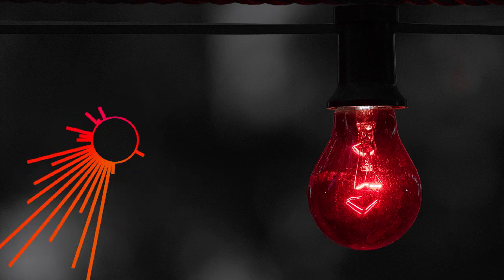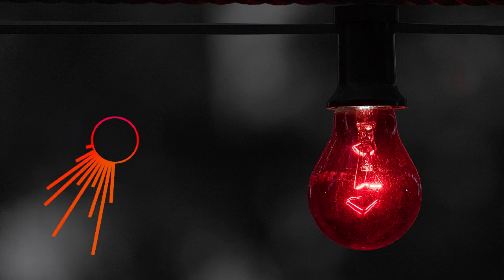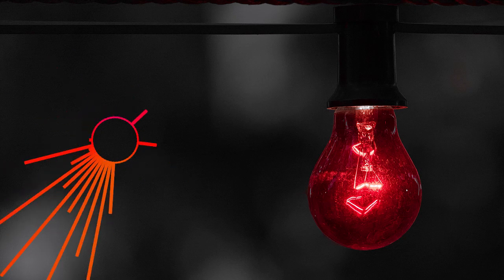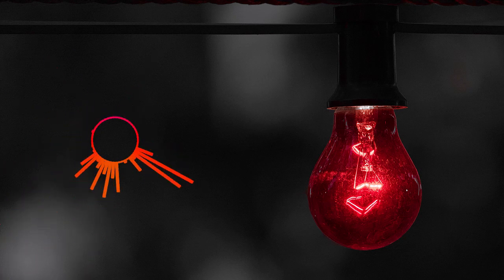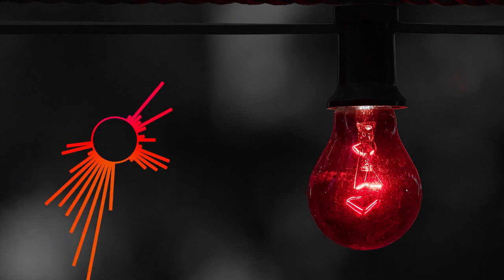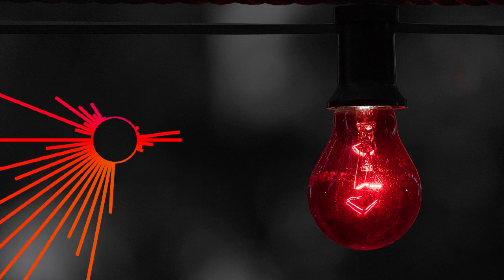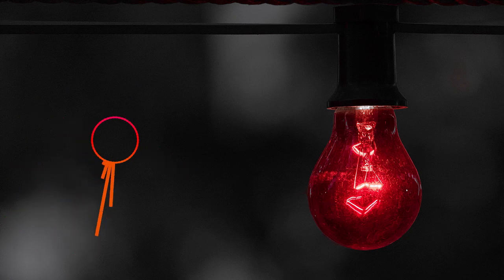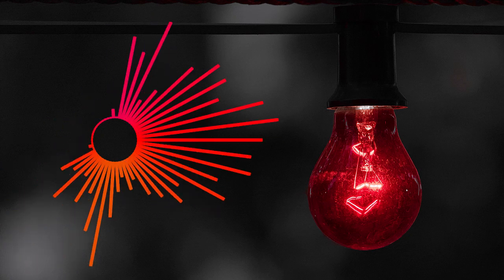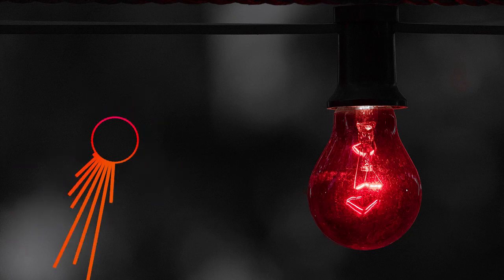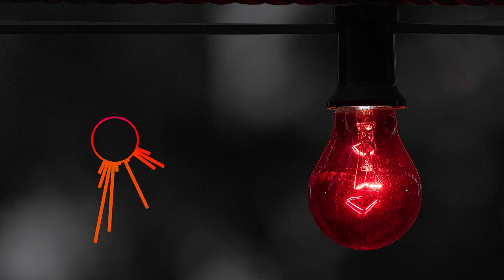Each lighting circuit has limits, just like a water pipe has a limit of how much water can flow through it without bursting. The limits are based on the size of the wire. Thicker wires carry more power. The wattage of the lights. The breaker size, which protects the circuit from overloading. A good technician knows how many luminaires can be safely connected to a single circuit based on these factors.